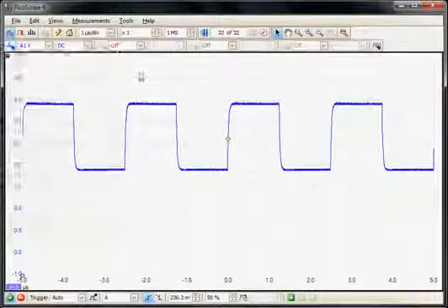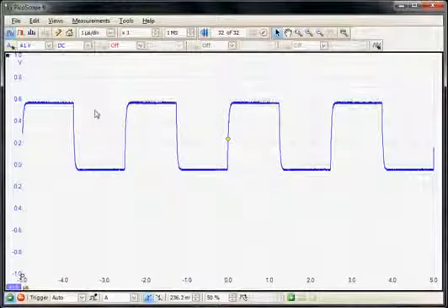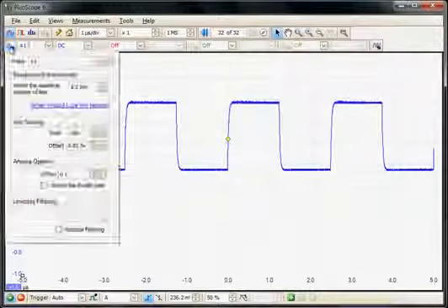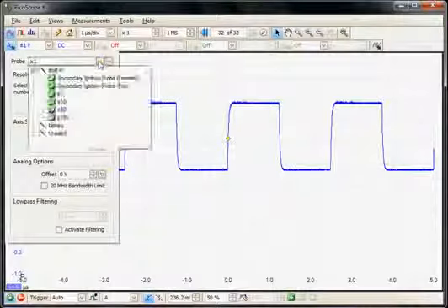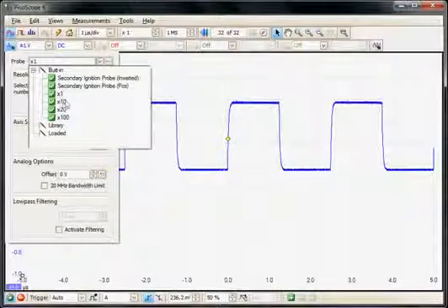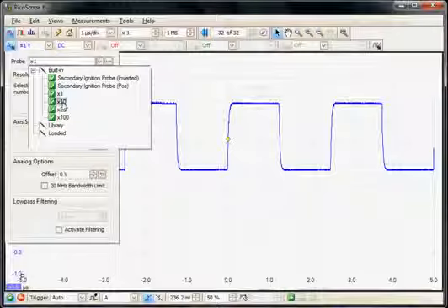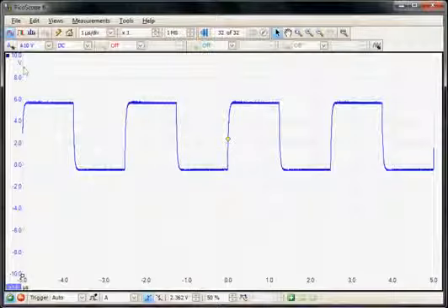library. So for example, I have at the present connected a ×10 probe to the channel A input. So to make the scale factors read correct, I will use the internal library for a ×10 probe. I'll select that, and what it's done, it's rescaled the vertical scale to plus or minus 10 volts. So for example, this is reading correctly now for a TTL input on the ×10 probe.